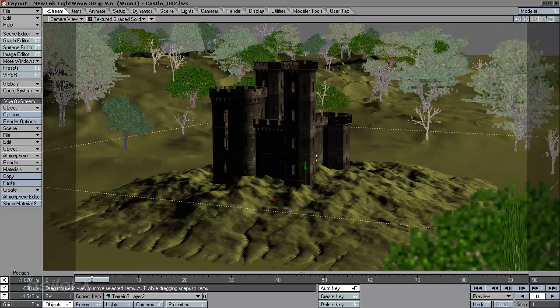I also want to note if you're having any performance problems, in your video card settings, you can turn off the transparent anti-aliasing, which can improve the overall system response, because these billboards are going to be hogging a lot of resources if it's anti-aliasing through the transparency and the objects themselves.